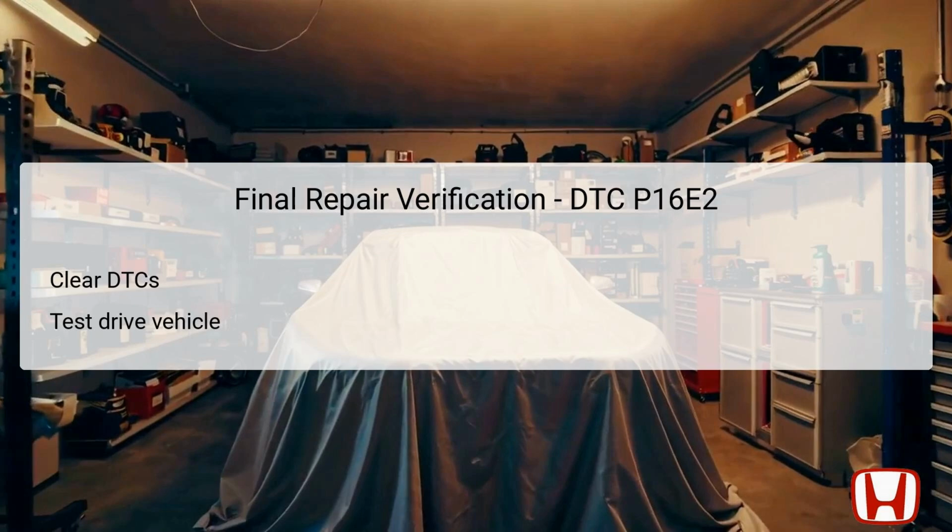Following the reset, it's crucial to take the vehicle for a test drive to allow the PCM to re-establish communication with the alternator through the LIN circuit under real-world driving conditions. This step validates the repairs made have been successful and confirms that no further DTCs are triggered post-repair. Monitoring the vehicle's performance during the drive will help ascertain that all systems are functioning correctly and any irregularities can be quickly addressed. Final verification is vital for ensuring long-term reliability and performance of the vehicle.